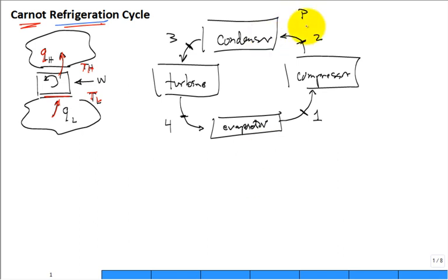Okay, right. So maybe we go ahead and talk about the pressure. How about the pressure difference across the condenser? What about the relationship between P2 and P3? P2 and P3. Aren't they the same? That's a standard assumption with heat exchangers, and that's what the condenser is. It's just a heat exchanger. And likewise for the evaporator, P1 is equal to P4.